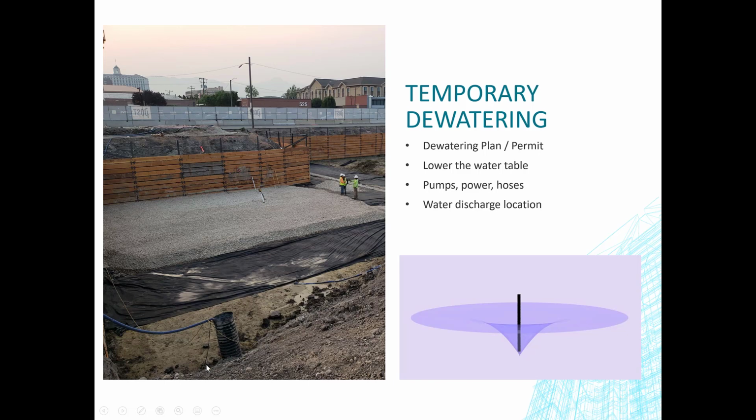or maybe they just dug a big pit, lined it with filter fabric, dumped gravel in it, put this ABS pipe in it, and the ABS pipe probably has holes cut in it down at the bottom so the water can get into this, and they can then put a pump down there, and you can see the hoses dewatering over there. You can see another one over here, so they probably got another dewatering pit over there.